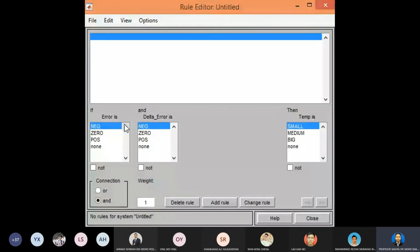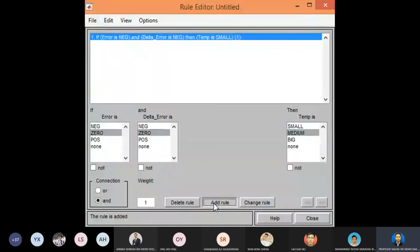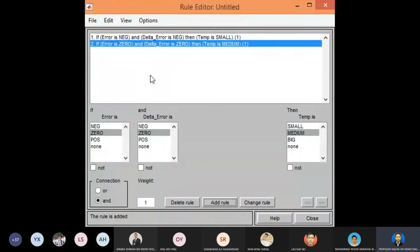First, you have to draw the matrix table. From the matrix table you can write the rules. For example, rule number 1: if input number 1, the error, is negative, the condition is N here, then the output I put as small, and you can add here. Rule number 1 will appear. Rule number 2, I set 0, medium, for example, and add rule. So rule number 2 and so on. Rule 3 I set as big.